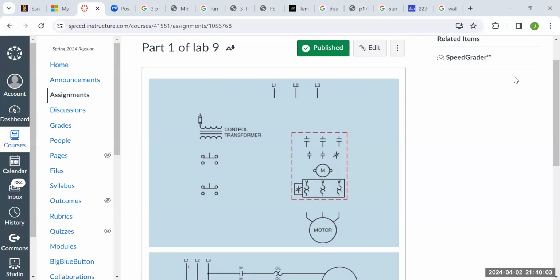That means the whole time that you want the motor to run, you got to push the start button. And then we're going to wire it also with a holding circuit. So once we put in the holding circuit and you push start, the motor is going to stay on until you push stop. So we're going to wire the stop start push button 2 ways, one with a holding circuit, one without.